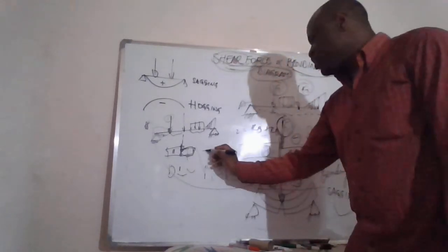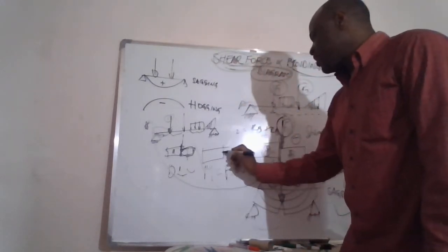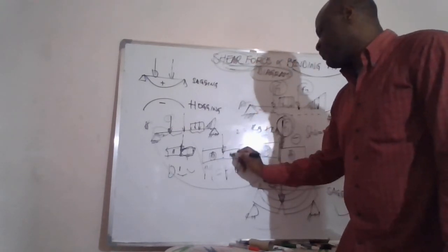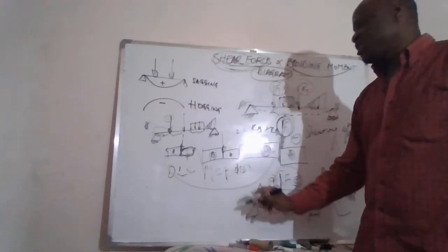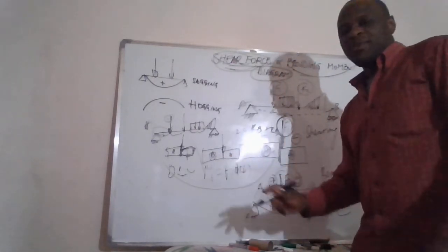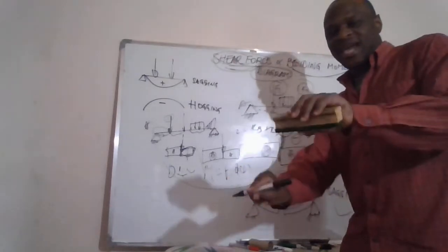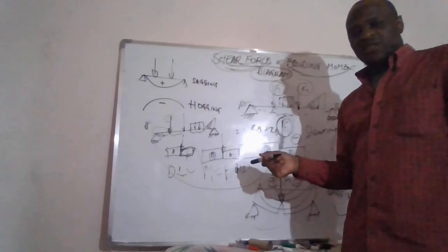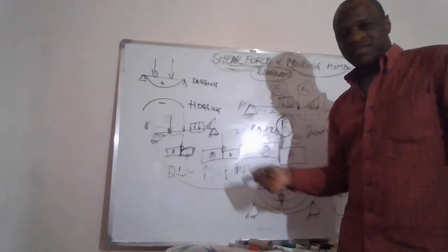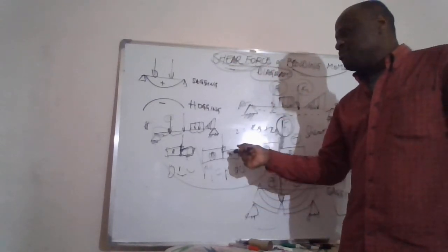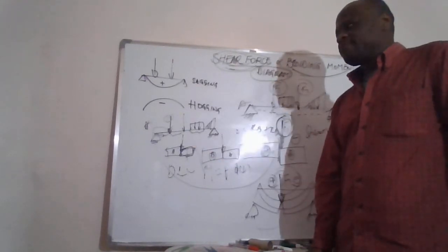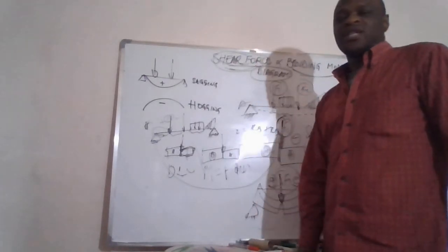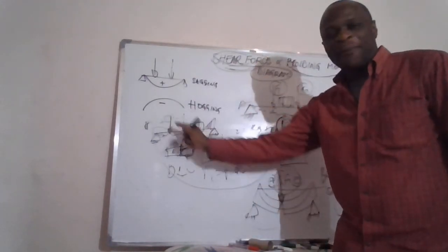Now, whenever there's a shear force, we always remember that the load has a tendency of making a cutoff of the beam on a cross section, making one portion of the beam, one span of the beam, slide over the other one. This is known as a shearing effect, which is one of the modes of failure for beams under applied load. And there's a positive shear force and negative shear force that can be generated when loads are applied on a beam.